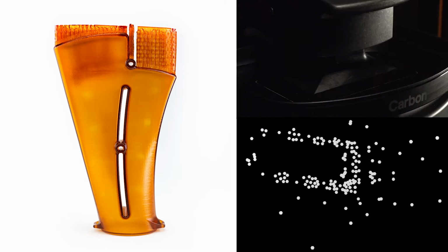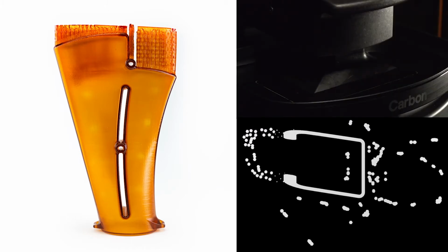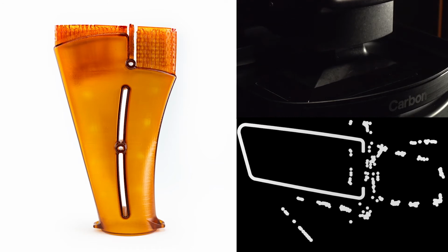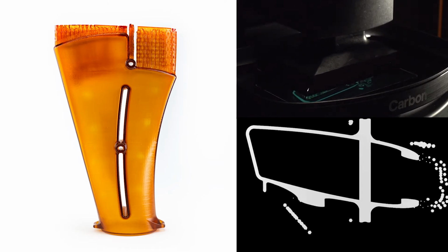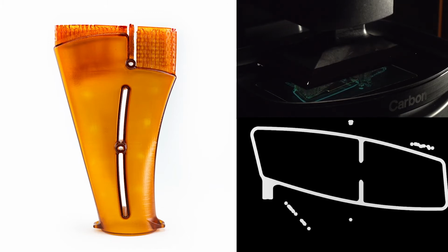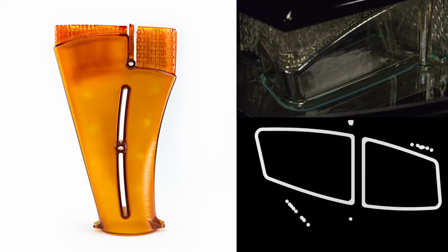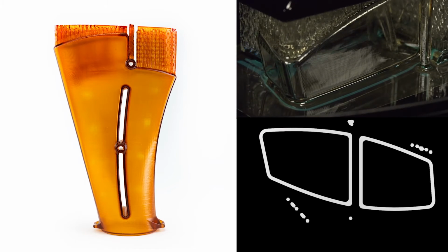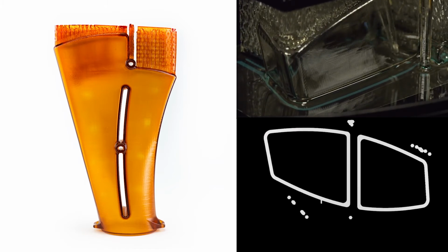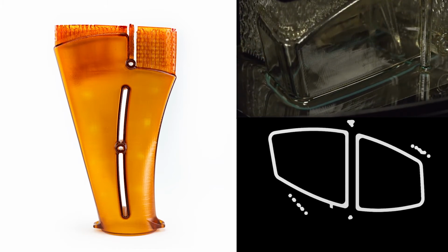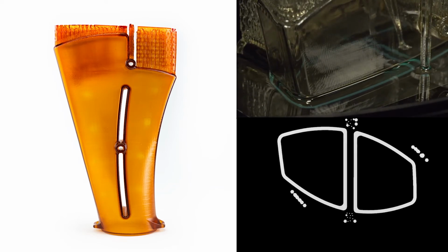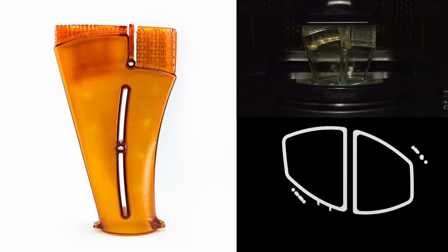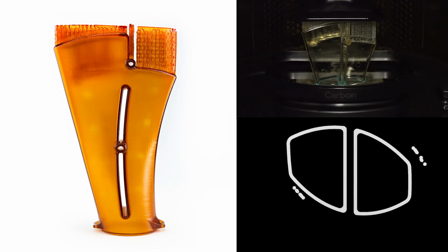Now, where our process differs from other technologies is we're not a layer-based system, so we're not sending slices to the machine. Rather, we are converting the geometry and the print setup into an alpha channel movie. An alpha channel movie is kind of like a bitmap movie, a black and white image sequence over time, played at a certain frame rate for the material chosen. So all of the UV is coming up through the white part of the movie, and anything that's black is blocked out.